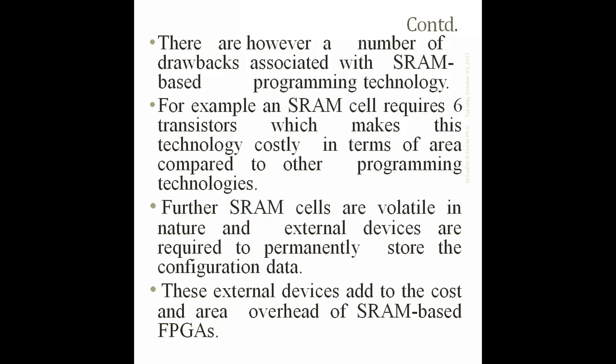It is costly in terms of area occupation. When you have a dynamic RAM, only a single transistor is sufficient to store the data, but refreshment is required in the DRAM. Further, SRAM cells are volatile in nature, and external devices are required to permanently store the configuration data.